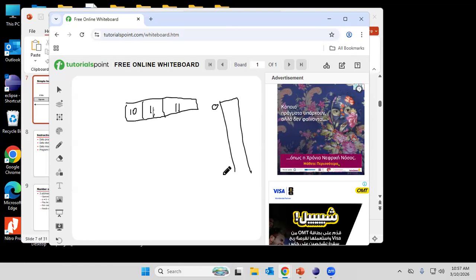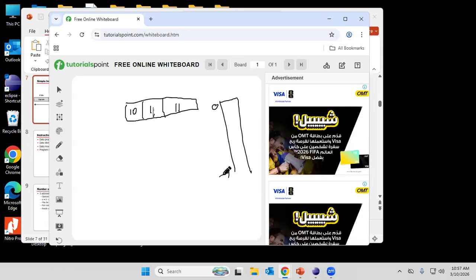Please help me out. What is the maximum RAM I can get to? Come on, guys. Somebody say something. Okay, you don't want to say anything, and it's 2 to the power 11, because this could be accessing memory, loading something and something. I divide them evenly, just pick for something. They can be in different ways. So the question is 0 to 11, that's only to what? 2 kilobytes? 2K addresses, 2K.